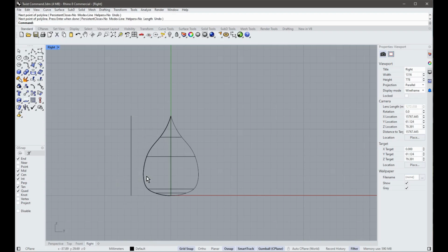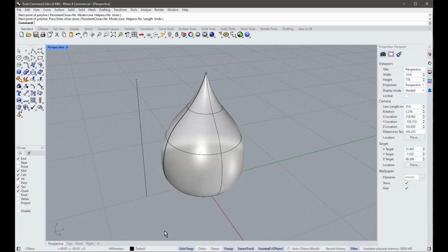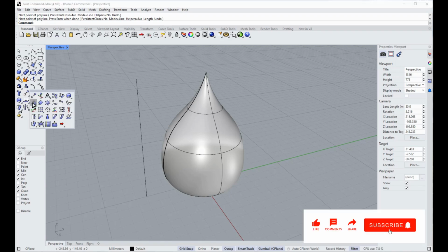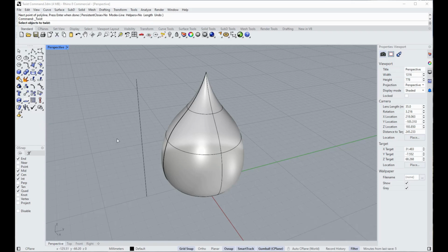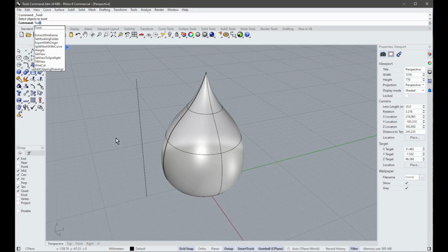So they're setting basically the radius out from the center and then how tall this thing is. I go back to perspective, and the command is twist. It's also under this menu on the standard ribbon. This is Rhino 8, of course, and we got the 3D text objects, and then right next to it you got this little box going over another box. You expand that more, and you got all these modifier commands down here, and this one is twist. Or you can just type in TWI, and it'll start to auto figure out what you want to twist.